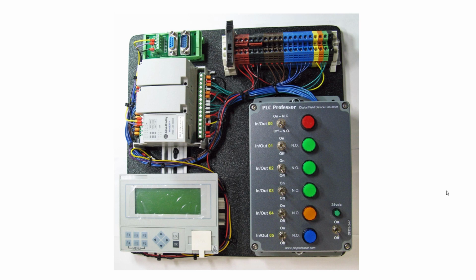Notice also that I'm using 6 inputs, but I have other inputs connected to those blue terminal blocks up at the top. Up at the top, that green terminal block is an extra output, an unused output from the controller that's not used for those 6 lights. The orange and the yellow is high-speed counter. Orange is high-speed counter, and yellow is analog output.